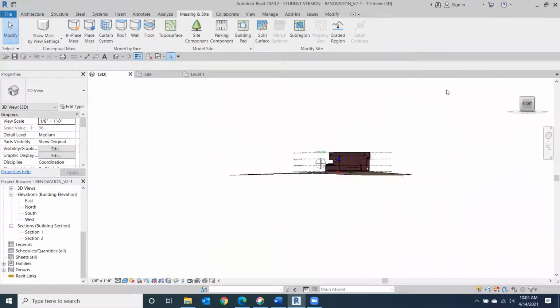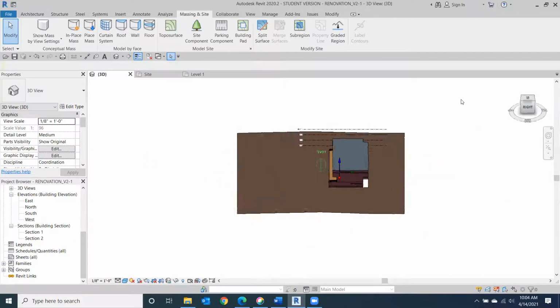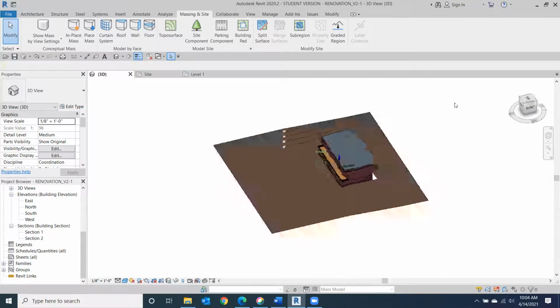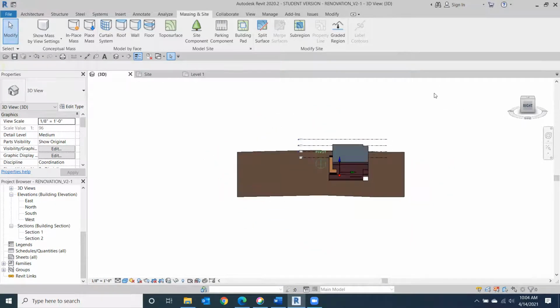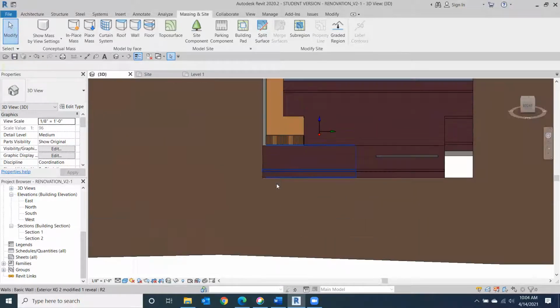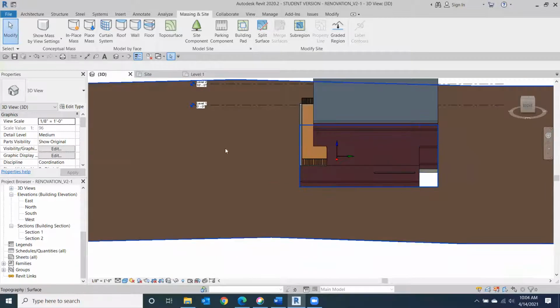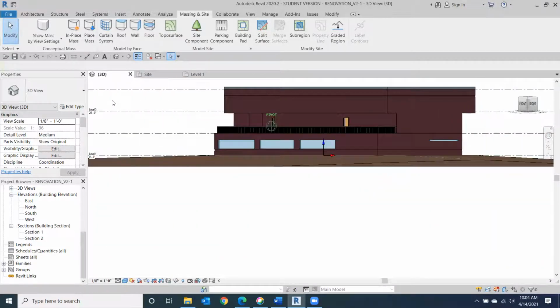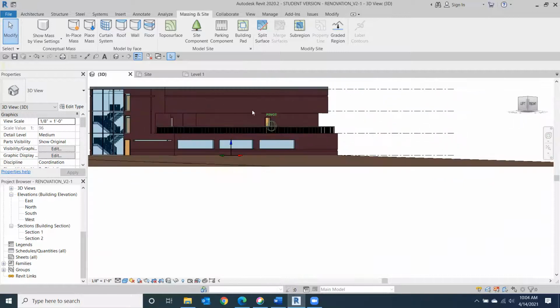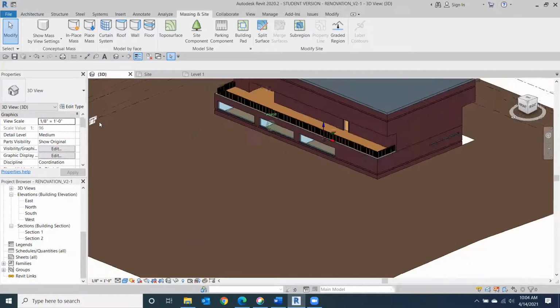Whoosh. So now I have my building nicely set flat on my site itself, which is pretty nice. So you see, this is what you're looking for, something where the two sides meet. This is why we go around the perimeter of the building, because we don't have these large gaps. If I wanted to at this time, I could go back and add a little mini site right here, and a little piece of topo surface and make that like a little garden or something like that. So that's not a problem. So that's how we're going to add some different elevations to our site. Any questions about that before we move on?